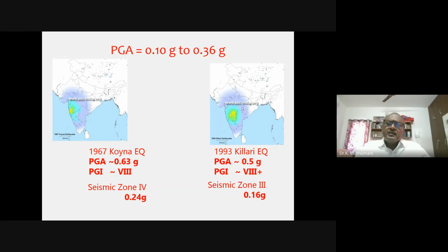So that means I am not saying that you should design for more forces. Please don't mistake me. You should design only as per code. There is no doubt on that. But the only thing is you should keep in mind that the real forces that are going to come on the building are likely to be as high as 2 to 3 times what you're seeing here. This is a real experience, and you should know this. How you are going to take care of this is what we are going to see in the rest of the time.